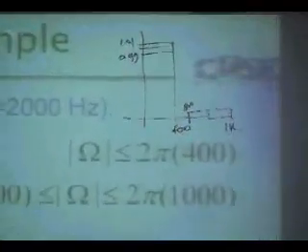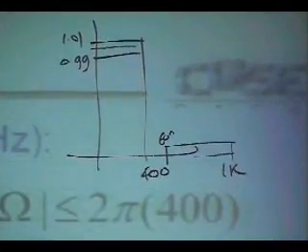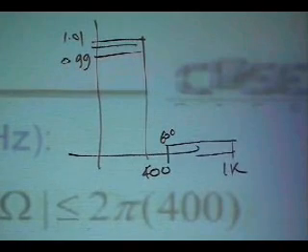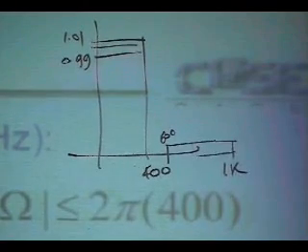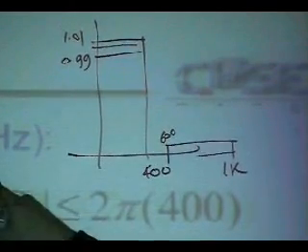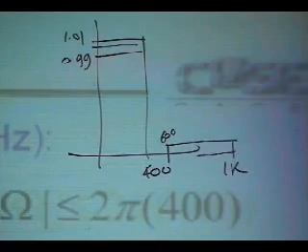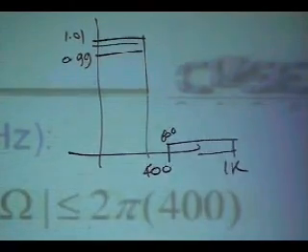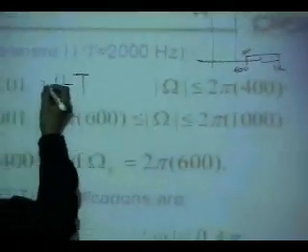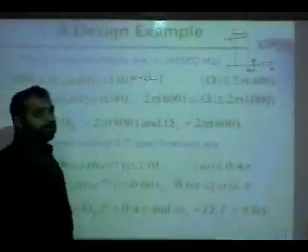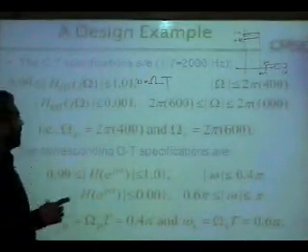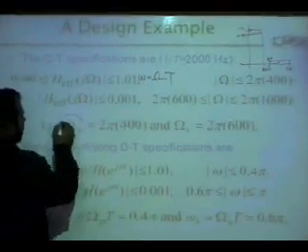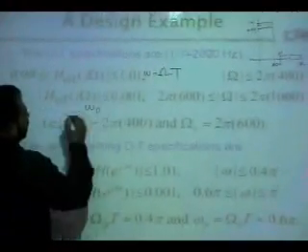So you ask MATLAB to design this filter. You can always convert these into small omegas. Okay, the digital filter specifications. And what is that? If this is your 1 over T is 2 kilohertz, so pi will be this. So you know the relationship that small omega is capital omega into T. So you can find out from omega p, you can compute small omega p.